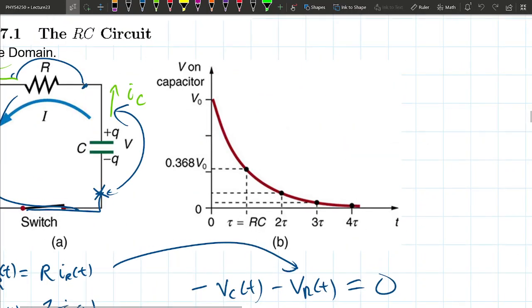Yeah, so if you plot the voltage across the capacitor, you start off with some initial voltage, 10 volts, 5 volts, whatever that starting number is. It'll fall exponentially, okay? With the characteristic, we're going to call this thing tau. It's the characteristic time. It's the decay time of that particular circuit.